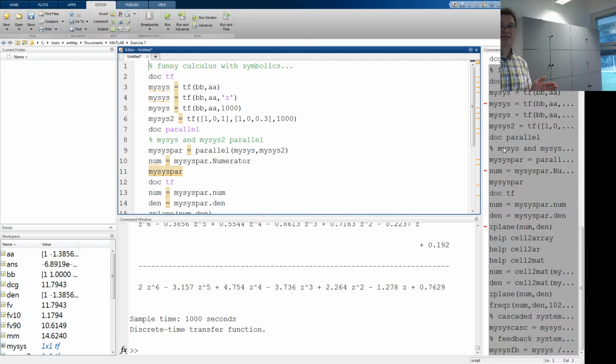I would guess the rise time will be better. I'm also guessing that the overshoot should be higher. Then you think, okay, the overshoot value is maybe because the derivative term is not high enough.